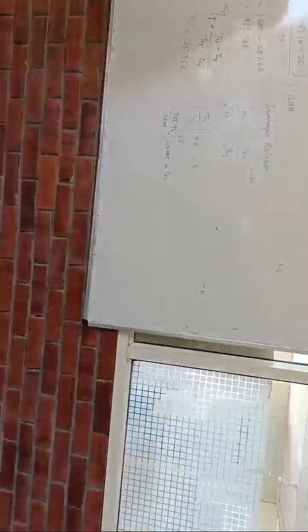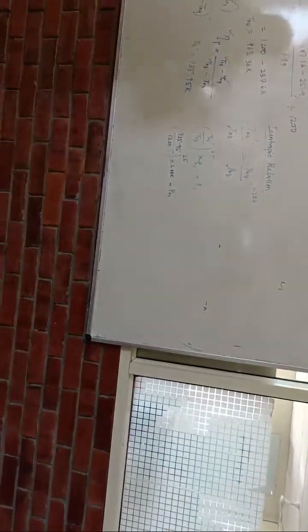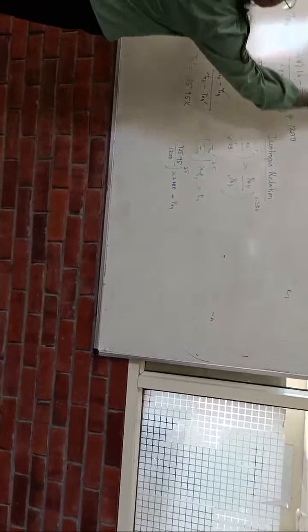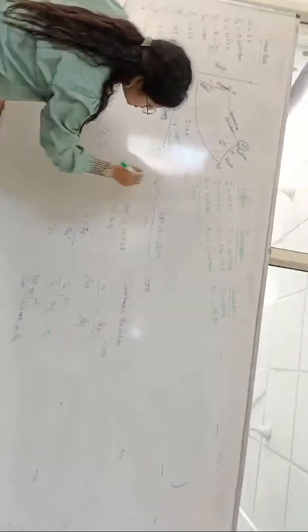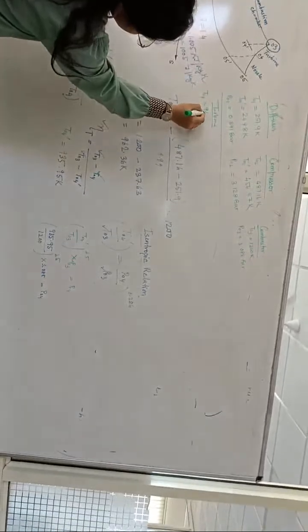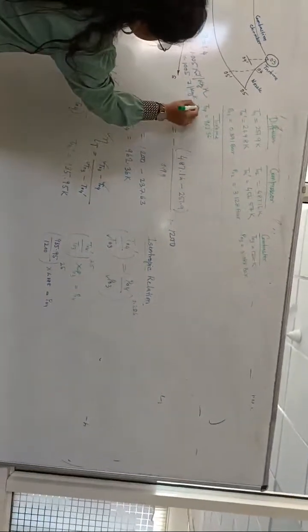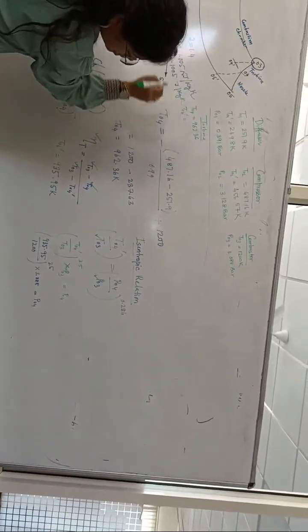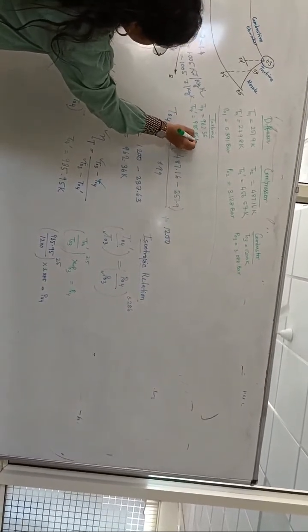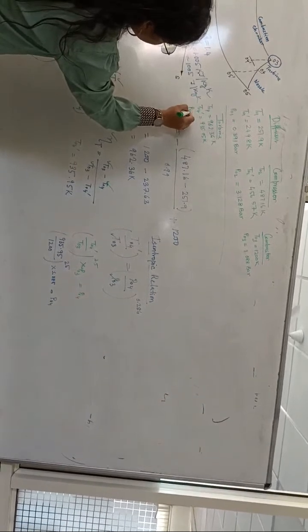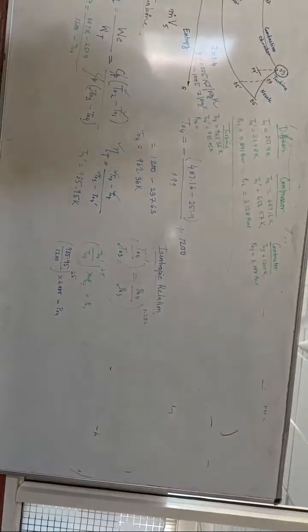Now quickly tell me what is P naught 4. Meanwhile let me write the turbine values. T naught 4 value we got is 962.36, T naught 4 prime is 935.95 Kelvin, and P naught 4. I'm waiting for your answer.